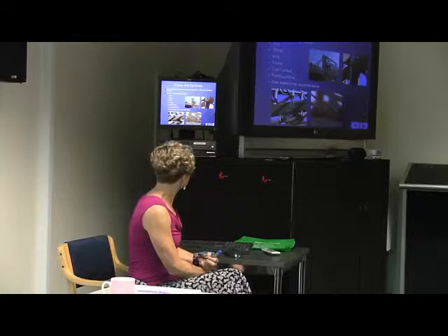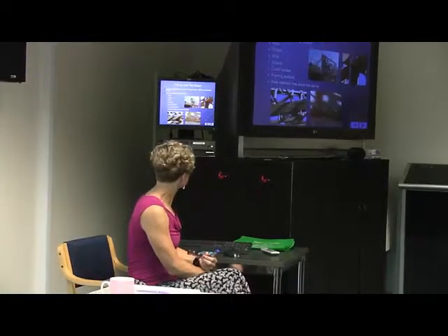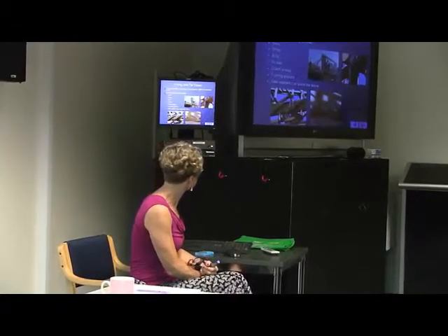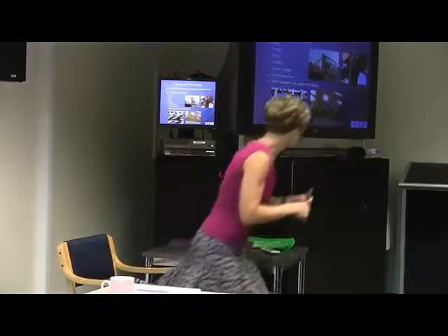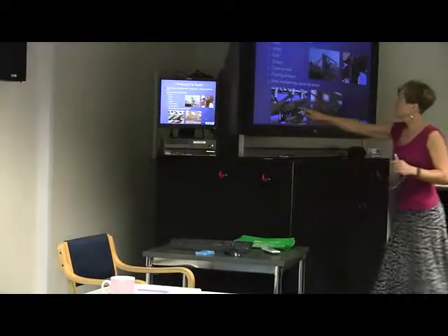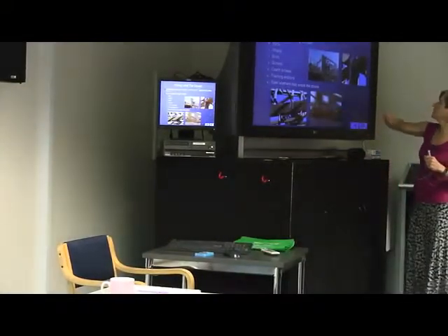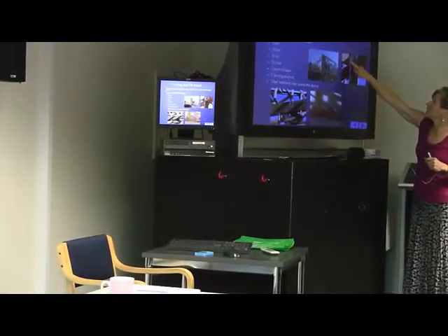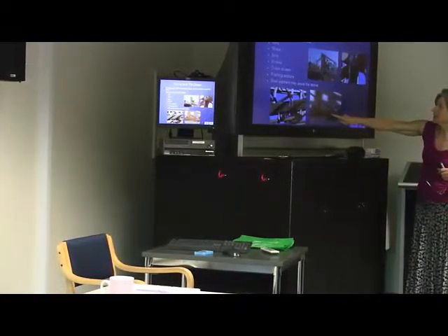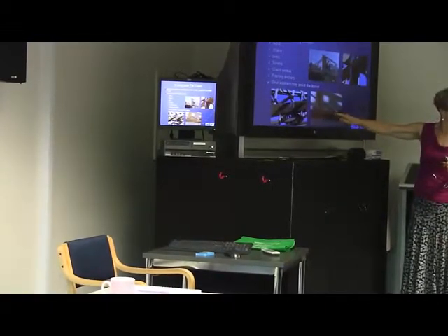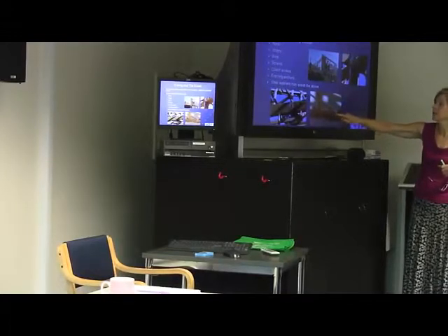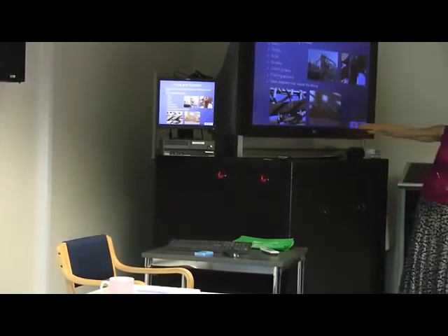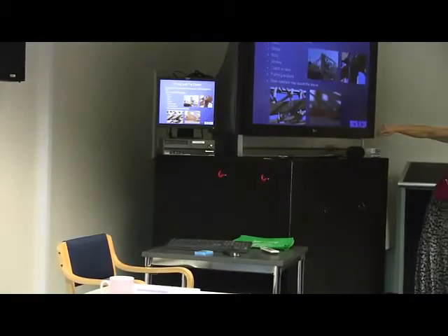These might be nails, they might be straps, bolts, screws, coach screws, framing anchors, steel washers. Okay, and there's a picture of a few of the types of tie downs that you have. So typically a metal strap such as that one, this is a metal strap as well, and there's also a connection between the rafter there and the top plate. There's a holding down bolt in the bottom plate of the wall frame into what looks like a concrete slab, but could be, yeah,